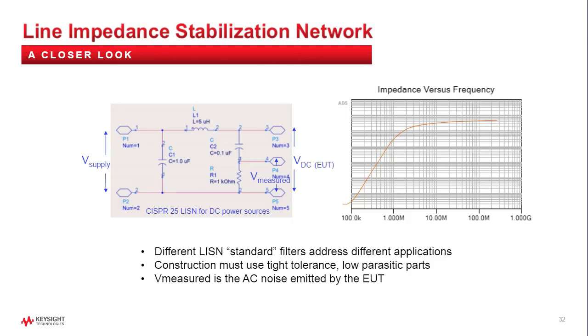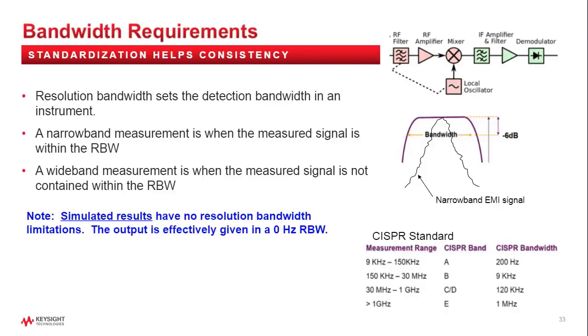Now this tap point here in the middle, pin 4, is where the measurement will take place, the conductive measurement. A couple more things to consider. In the chamber, we're going to use a spectrum analyzer, which is a tuned radio. In the simulation environment, we have to come up with a way to simulate the measurement behavior of a spectrum analyzer. And the simulation is going to be a time domain simulation.